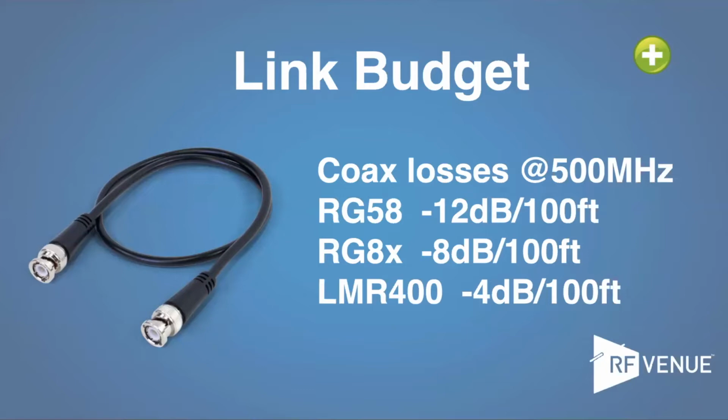So these are typical wires. RG58 is the little antenna wire that everybody's used for forever. I recommend you don't use that anymore. From this day forward, no longer buy RG58. RG8X is a much better choice. It's almost exactly the same size, pretty much a straight replacement, but you can see that the loss in RG58 is 50% more than the loss in RG8X. Plus RG8X is 100% shielded, so that's going to help you avoid some other problems.